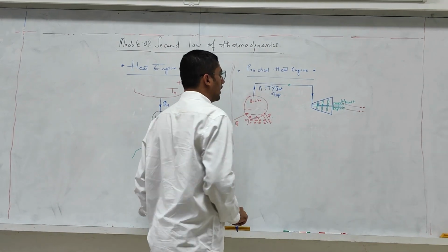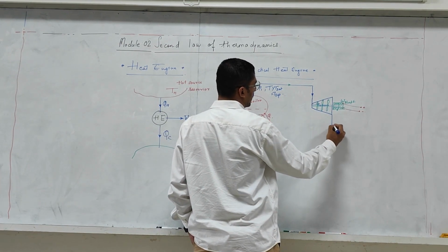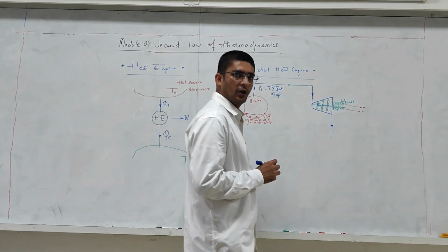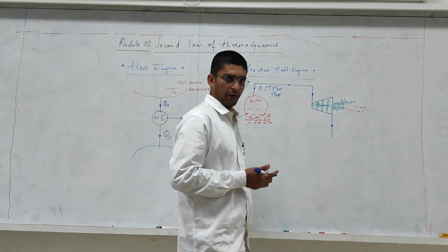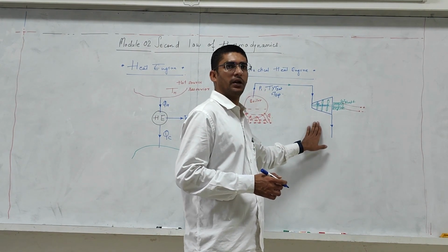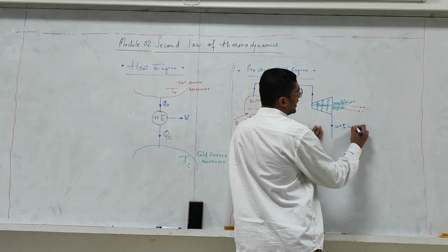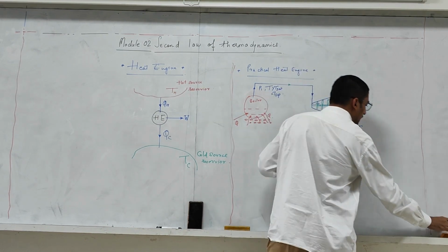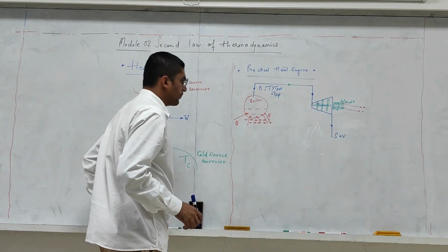Now what happens ahead? When the steam leaves the turbine, it is at low pressure and low temperature. It might happen that some amount of the steam gets converted into liquid. So over here it is not guaranteed that we have a saturated liquid; for example, with water, we don't have 100% water here. It is usually not possible. We have some steam and some liquid. It depends on the pressure and temperature at the outlet.